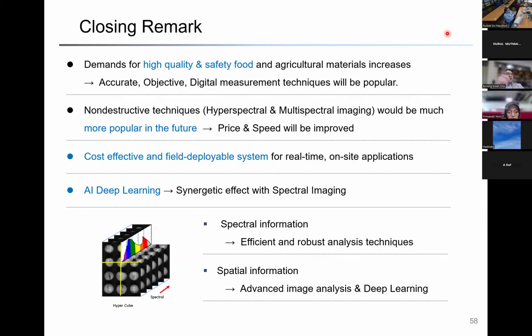So if the measurement takes 1 minute, the measurement starts at short wavelengths and then moves to longer wavelengths. While measuring, the temperature changes. The sensor response will change, and your spectrum will be skewed. The slope of your spectrum changes. That is the environment effect.